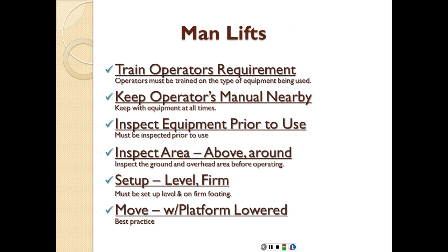Now for another type of scaffolds, the man lifts, trained operators requirement. Operators must be trained on the type of equipment being used. Keep the operator's manual nearby to identify again the proper height, to identify the proper loading, etc. Inspect equipment prior to use. Inspect area above and around, especially for inconsistencies in the flatness and the level of the ground, or for the existence of power lines and things like that. Set up on level and firm soil, and move with platform lowered.